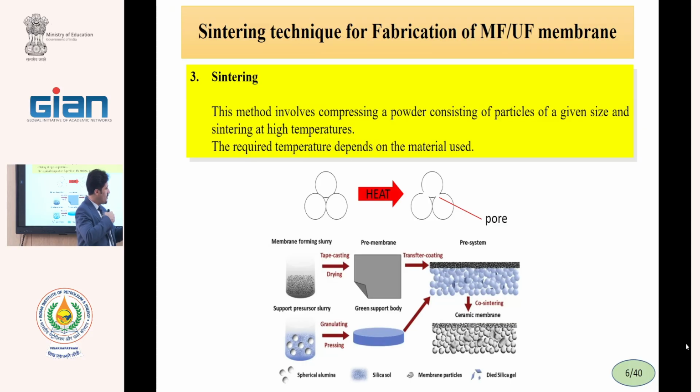prepared by high pressure pressing, but the stability of this disc, this film, is not suitable. And with a very low pressure, we can destroy and break this disc. For increasing the stability, we should sinter the obtained pressed disc for attachment of the particles together.